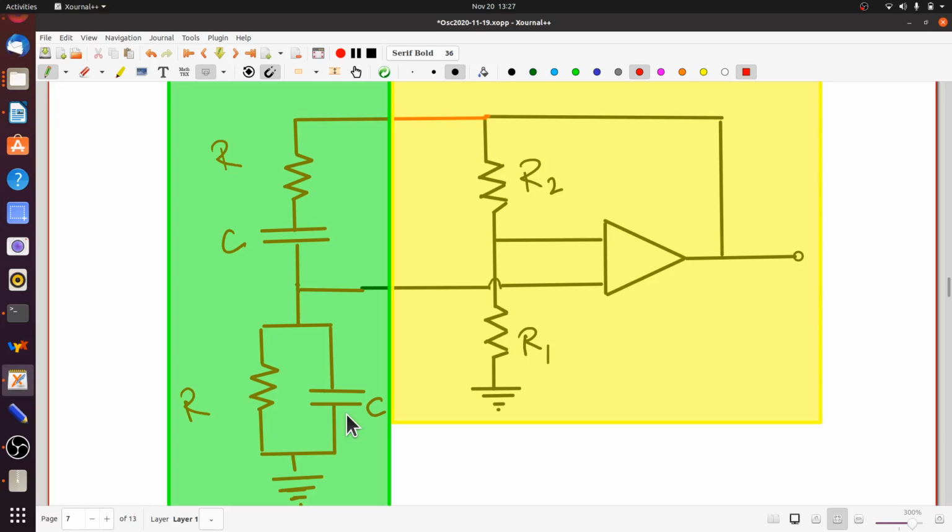There, the original circuit essentially involved a situation where R2 was a resistance and R1 was replaced by a bulb, a standard light bulb. Now, why is that a good thing? Because a light bulb has a resistance which depends on how hot the filament gets.